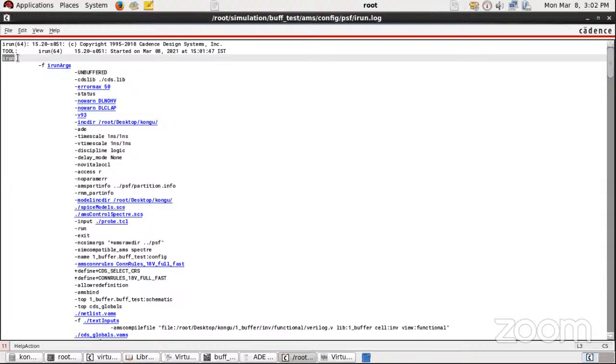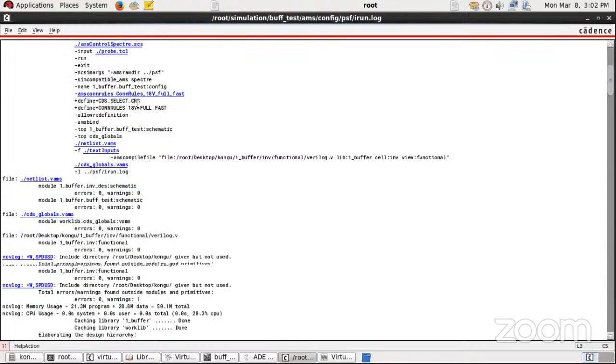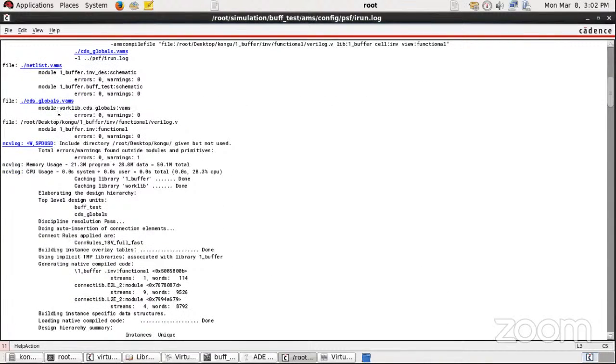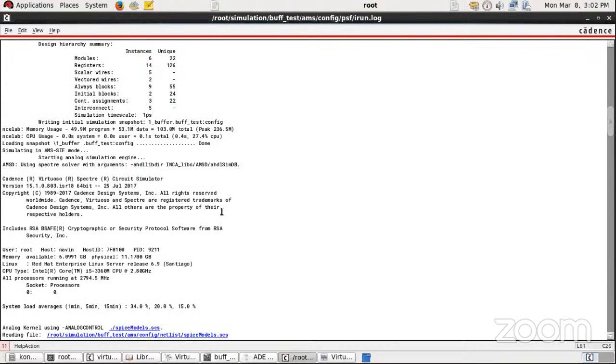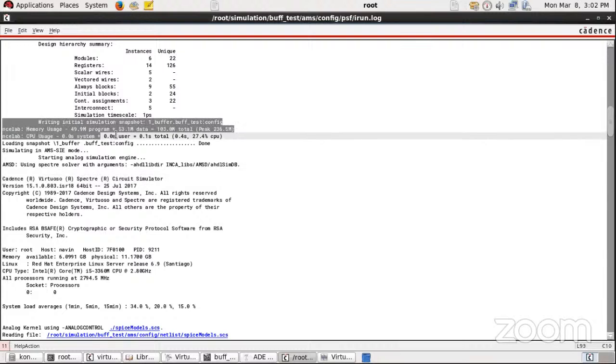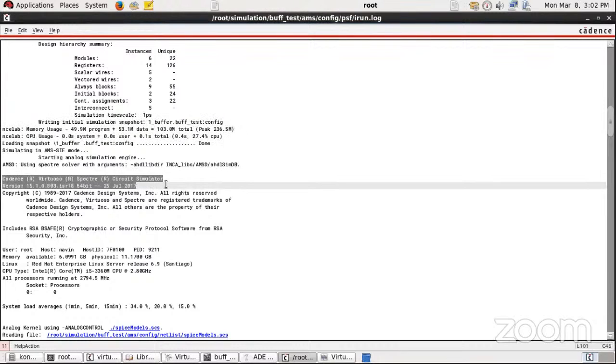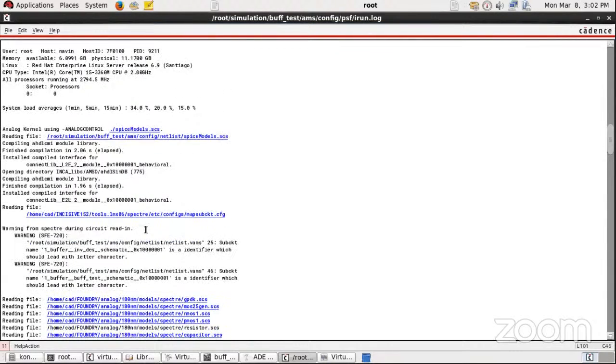Okay. Just for running the simulation alone. And for compilation, NC-Verilog. Okay. This is the name of the Verilog compiler that is used in the semi-custom IC design flow. Okay. The design is then elaborated and then mapped with Cadence Virtuoso. You can see the elaborator tool option, and then it is coming into the Virtuoso Spectre circuit simulator, and in that we are making use of AMS.